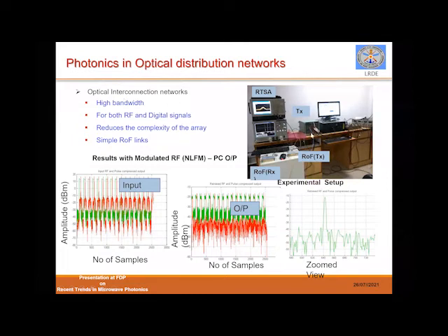And then you can see that this is a radar exciter, a conventional radar exciter, where RF will be generated. It is given to an RF transmitter, and then this transmitted signal is passed through a single fiber link, and it is converted back to RF with the help of an RF receiver, and then it is monitored with the help of an RTSA, real time signal analyzer.